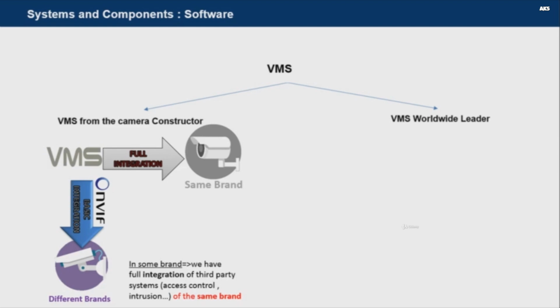So you will ask yourself what ONVIF Profile S is. To communicate how IP-based video surveillance products from different manufacturers are compatible with each other, ONVIF Profile S covers basic video streaming functionality, enabling the VMS to configure and request video streams from an IP camera or video encoder. So you are not locked into a single brand, and you can install cameras of different brands and see the video from all the different brands in the VMS. Just make sure that the VMS and the cameras are compatible with ONVIF Profile S. I repeat, ONVIF Profile S covers just the basic streaming functionality.